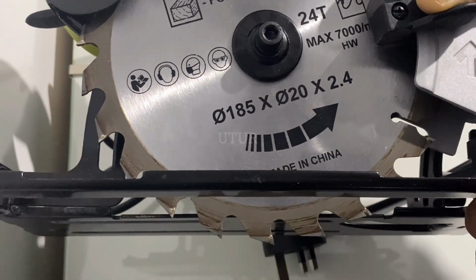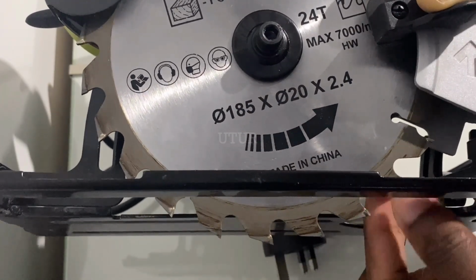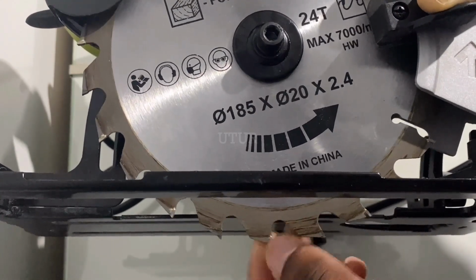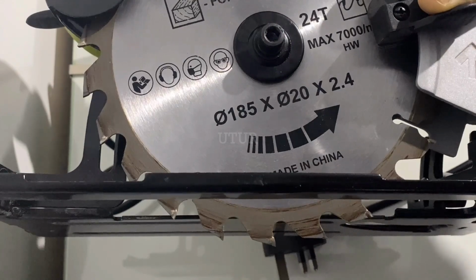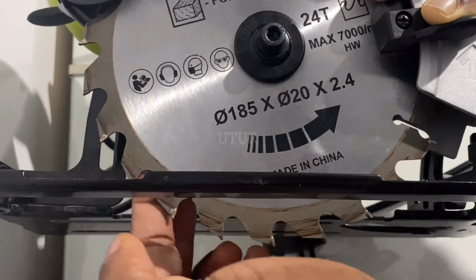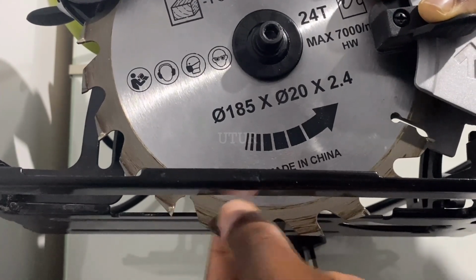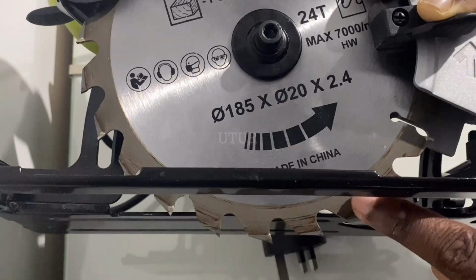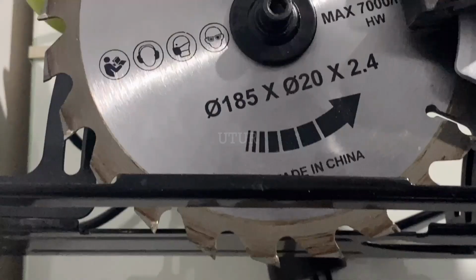So, what quality of cut can we expect if we proceed to utilize this ripping blade to cut strips from the hard plywood? I'd be expecting a somewhat poor quality cut, with excessive tear out in certain places. I would also be expecting overheating, okay?